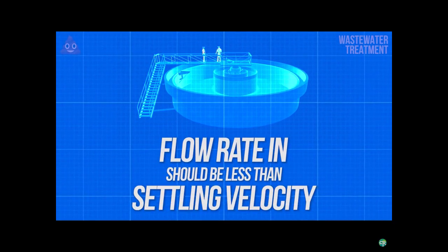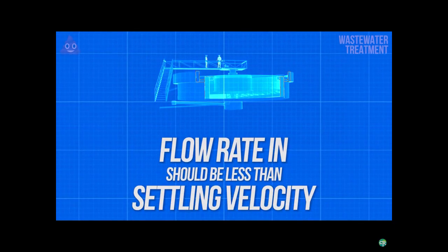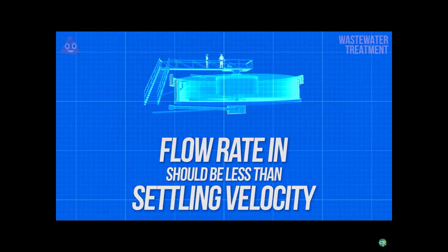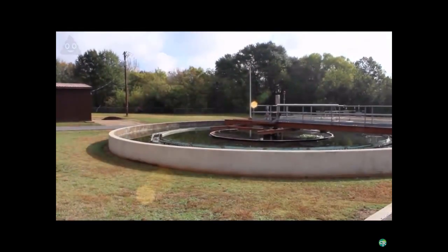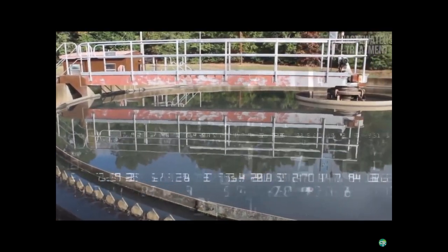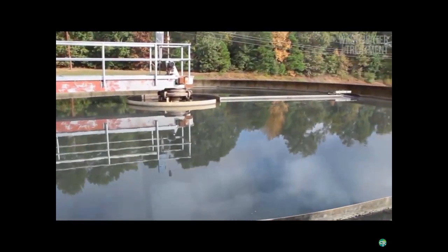In order to accomplish this, engineers will vary the size and number of primary clarifiers in accordance with the plant's permitted sewage flow rate. This ensures that at varying flow levels, solids can settle out of primary clarifiers to the correct quantities.